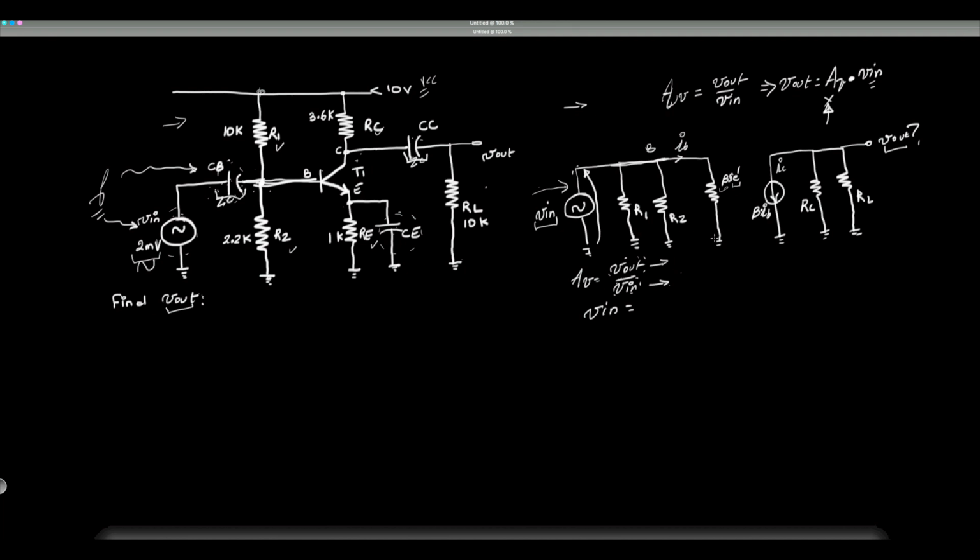In other words, it's the same voltage against the internal resistance of the transistor. So in other words, this is V in as well. Aha! If that is the case, then this V in is equal to IB, so simply Ohm's law, times beta times little RE prime.